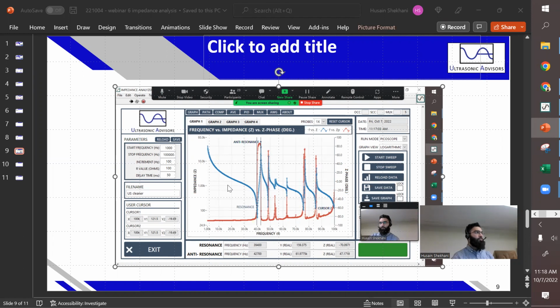The other question was, I noticed you use a picoscope as your 2-channel oscilloscope. Can you do frequency tracking with this? Yes, you'd be able to do frequency tracking. Now there's certain limitations on this picoscope, and I've run into those. I've tried something similar to this. You can actually do frequency tracking with this, with the generator, and you have to have an amplifier, obviously, because the output is 2 volts coming out of the picoscope. So you can use it, but there are some challenges that I ran into. I'll let you run into those challenges too, if you try to do it. That's all I'll say.